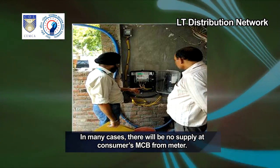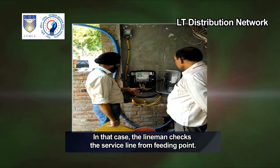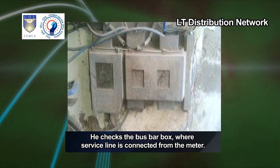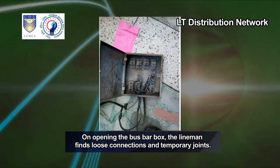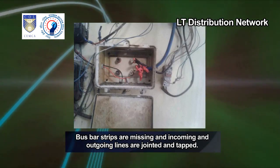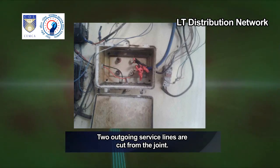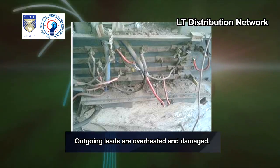In many cases, there will be no supply at the consumer's MCB from the meter. In that case, the lineman checks the service line from the feeding point. He checks the busbar box, where the service line is connected from the meter. On opening the busbar box, the lineman finds loose connections and temporary joints. Busbar strips are missing and incoming and outgoing lines are jointed and tapped. 2 outgoing service lines are cut from the joint. Outgoing leads are overheated and damaged.